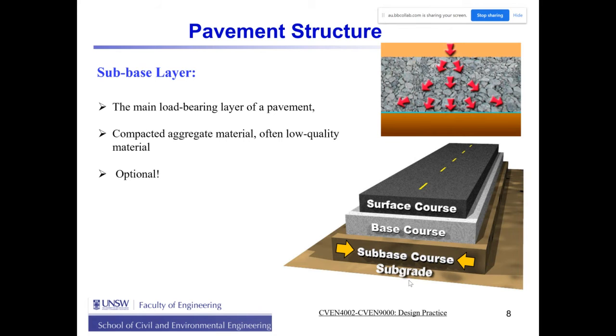Just with the surface layer and base layer, you can distribute the load and the level of load would be acceptable for the subgrade. But if you are designing a pavement for a heavy traffic road, then in that case, we generally need to design and consider subbase.